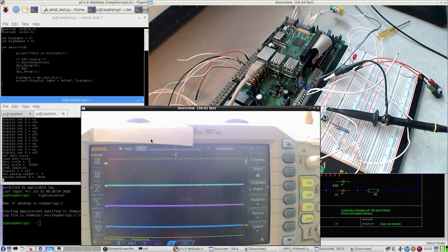Oscilloscope engaged, and only one probe attached, so these 3 lines are to be ignored now. And voltage is on 5 volts, so one cell is 5 volts. Then what you notice is here a flat bottom, so it gets truncated. But another thing is, if this is 5 volts, then why is the period so incredibly large?